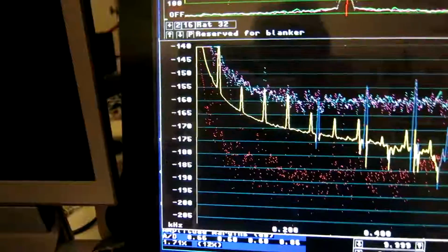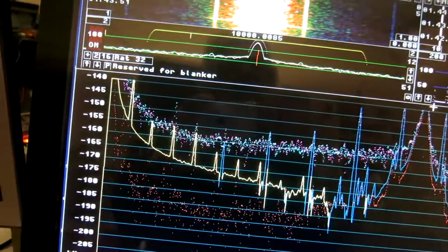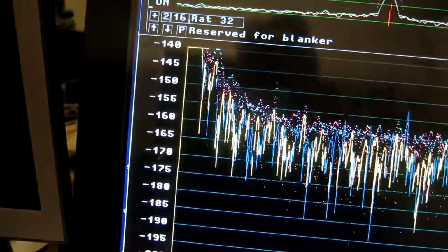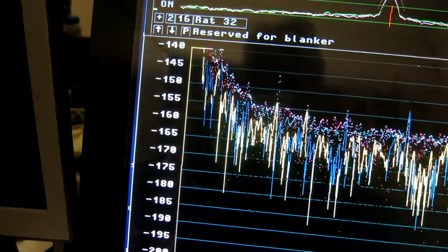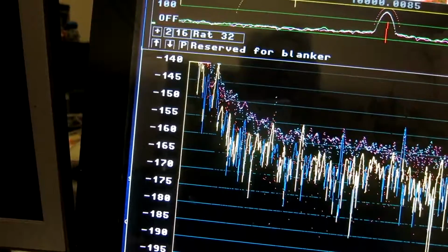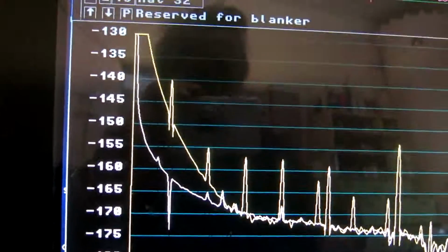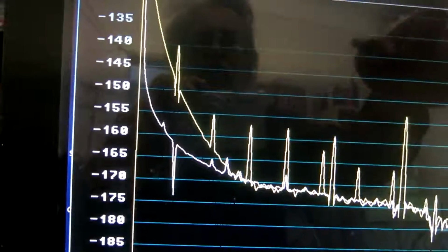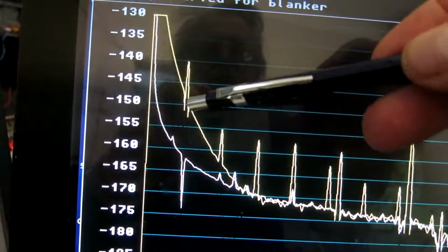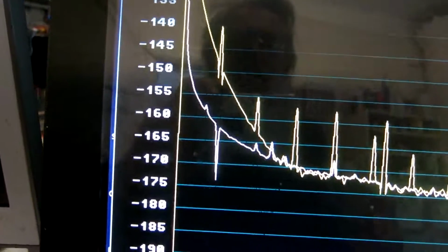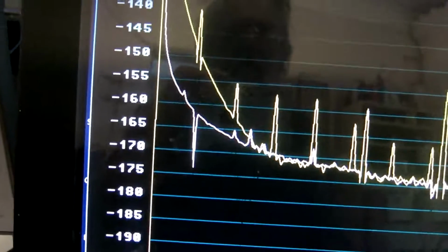So I look for phase noise, and now I clear the display and start to see in what way has performance changed as seen by this system. Now this is 12 hours later, or nearly 13. What I see is quite different from before. Phase noise seems much stronger. It's about minus 150 dBc per hertz at 50 hertz. But the amplitude noise is similar to before.